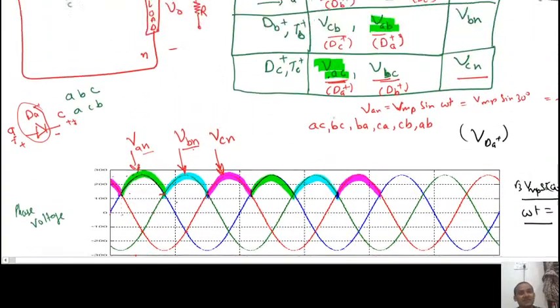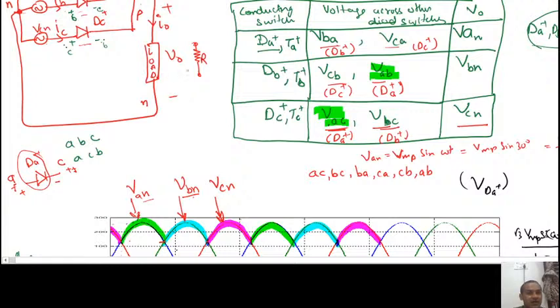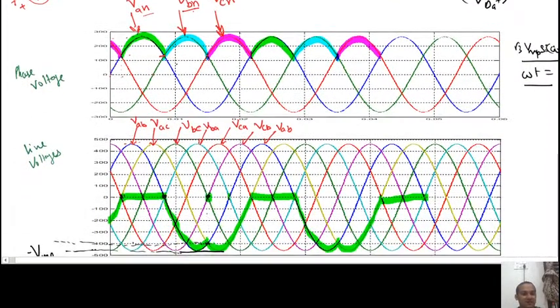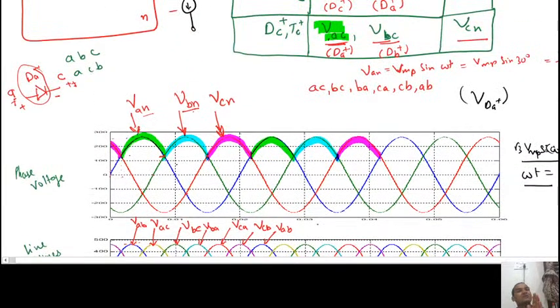You see here, it's very simple. Now instead of a resistive load, if you take an RL type constant current load, again you can see, since it's a diode, it doesn't matter what kind of load you take, because ultimately the output is going to be like this. In the case of an uncontrolled diode rectifier, the output voltage will be the same, and hence the voltage across the device will also be the same. The only difference will be in the current.